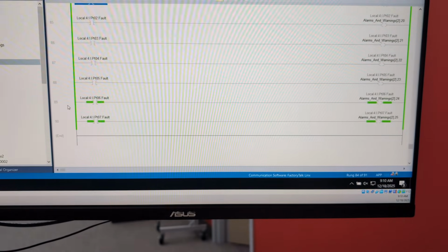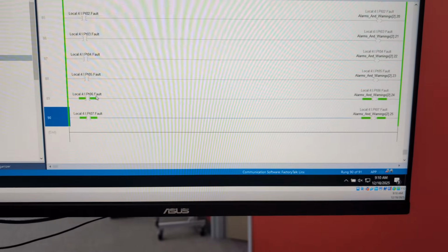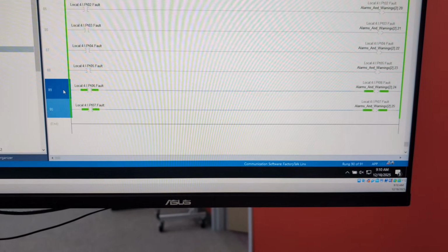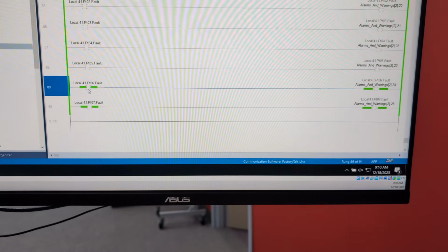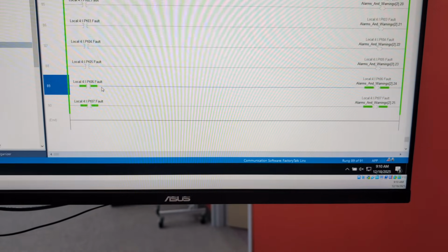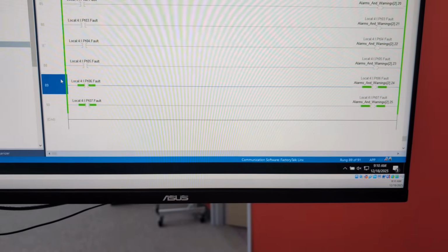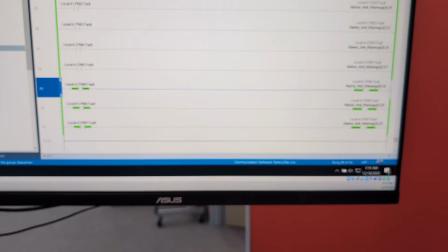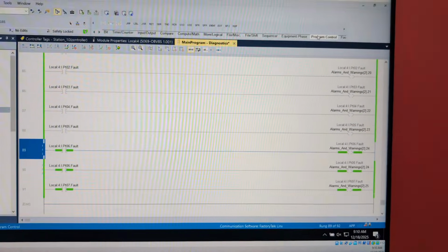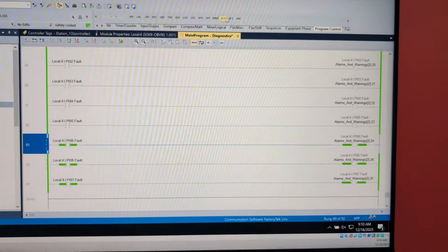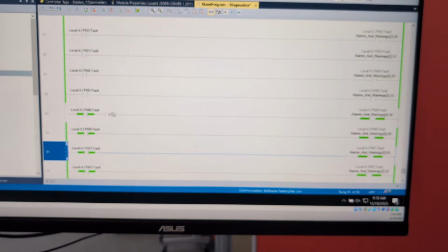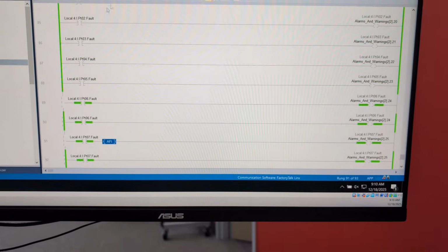Now, 6 and 7, they would have shaken themselves out during our startup and commissioning because they're not used. And here's a good example. A lot of people are like, well, why would someone put an AFI in? Well, if we're kind of OCD and we want all this laid out and we don't know if we're going to use 6 and 7 later, yeah, I probably would. Here's a perfect example where I would do an AFI. So I would go over here to my program control category, and up here we do have the AFI, which is an always false instruction. It does not disable or wrong, and we have a video talking about that. But yeah, we would do that.